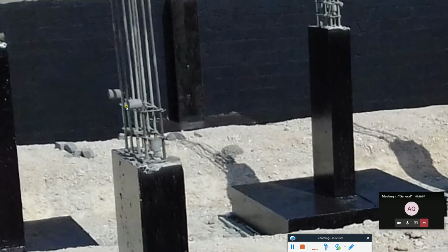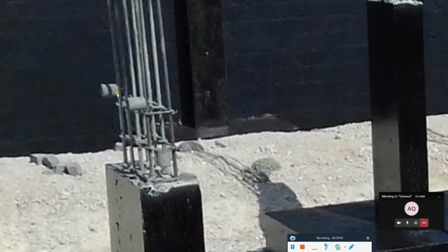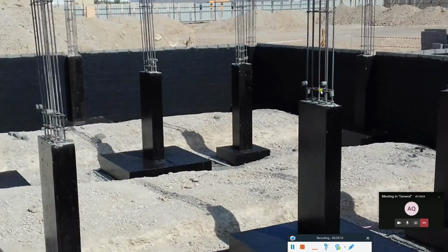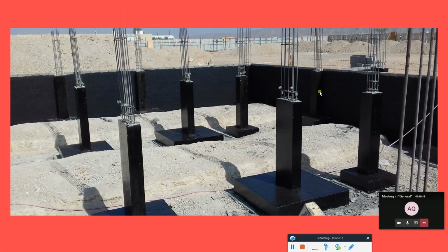You can see here, these are the cover blocks. These are the side cover blocks for the columns. Cover blocks can be done on the side. Some of them are using crushed portions of the blocks. They take the block, break it, and take a specified dimension. Some of them are making it on the side, and some of them are taking ready-made ones as well.